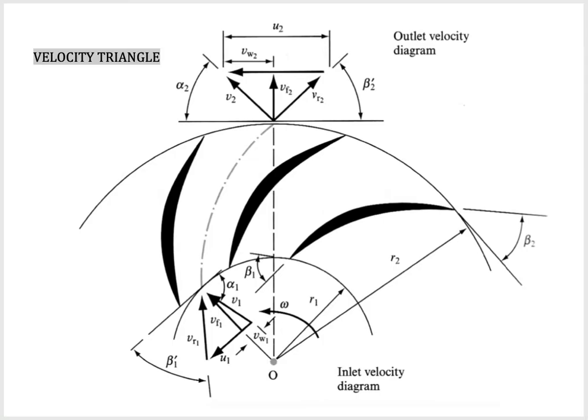Centrifugal pump, and for today we will discuss velocity triangle again and the types of blade. So this is the complete velocity triangle, and I hope you already know how to draw this velocity triangle because I have special notes on how to draw velocity triangle previously. So here we have a blade, and this blade is a backward blade. So this is the eye, the water comes from here.